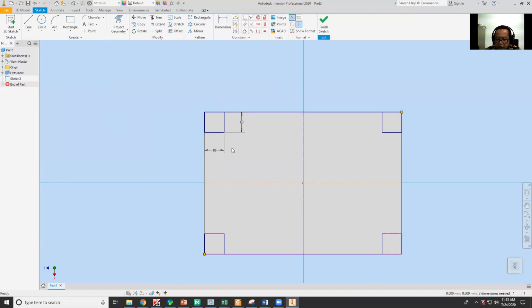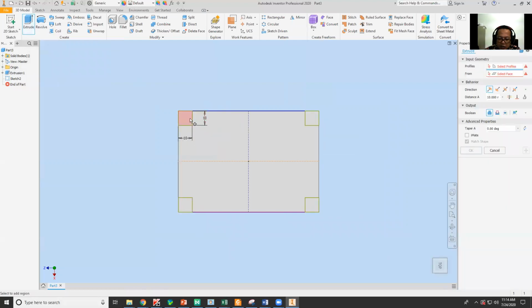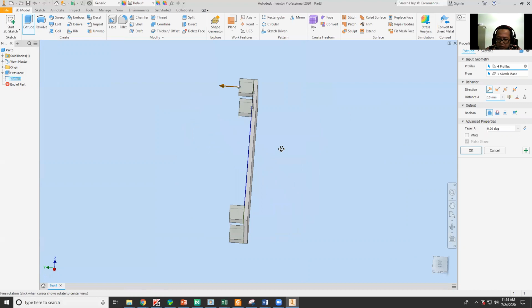Okay, the next we can make a extrude for this part. Yeah, extrude for this part. Okay, and then you can click isometric here, this one, yeah, the house, or you just click like this, yeah, extrude. Follow me, click extrude this part, this part, this part, and this part. Okay, you can click and hold the shift button, shift, and you can click the middle of your mouse, and it will be like this.